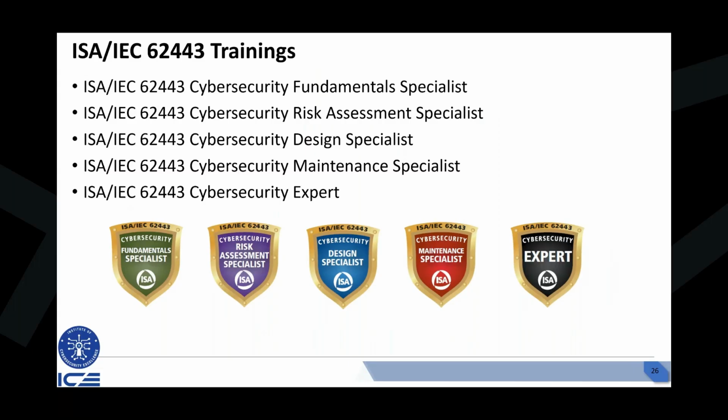In fact, it's very common to have segregation between, for instance, DCS controller and safety controllers, because they are in two different security zones. So when you define the zones, you may have two L1 devices in separate zones, and then you will need to put a firewall in between, or have some other kind of segregation in between.